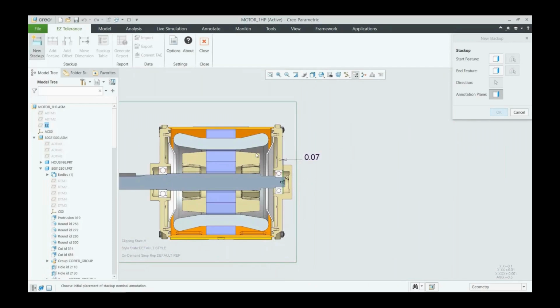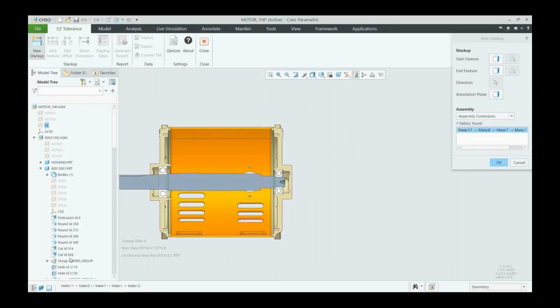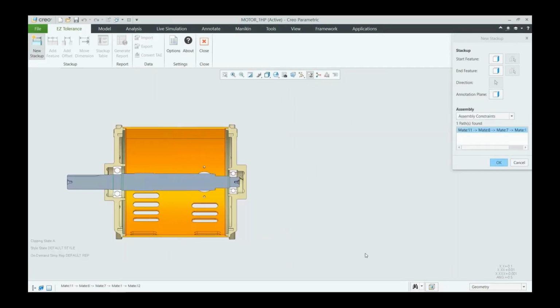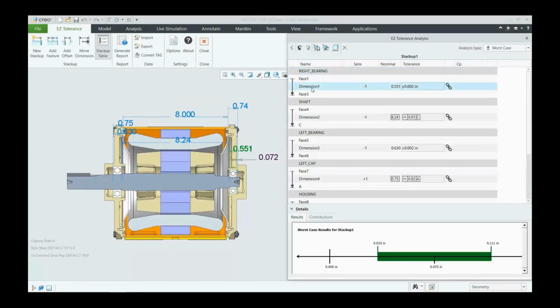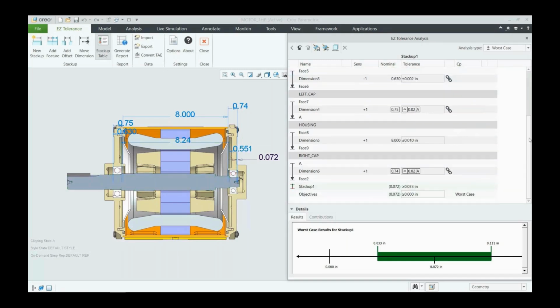So the problem is that most teams that we see, they define tolerances but don't actually analyze them. They work on a particular part, tolerance the part, but don't take a look at the bigger picture. And that becomes more of a box ticking exercise. So when parts don't fit right, or production fails a test, let's say, we end up stuck in that costly rework loop of trial and error and getting things to work. Or what can end up happening is you just end up tightening tolerances across the board to make sure you're safe, which drives up your manufacturing costs.